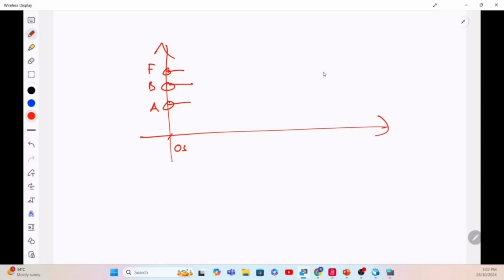The answer is based on the time precision that we use. If we write 1 nanosecond time precision, it means the simulation software, which is the ModelSim that we use, reads the input and evaluates the output every 1 nanosecond. So from time 0 to 10 nanosecond, the output will be plotted at 1 nanosecond, 2 nanosecond, and 3, every 1 nanosecond.